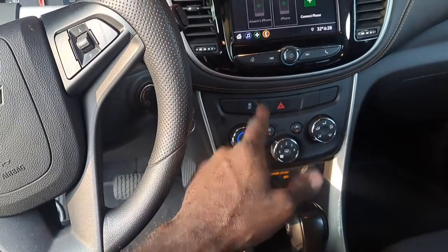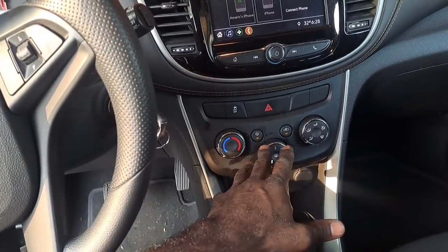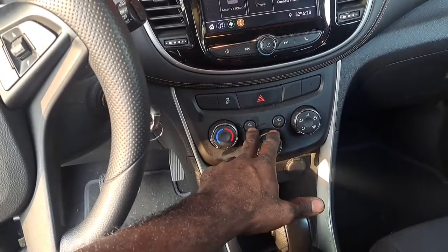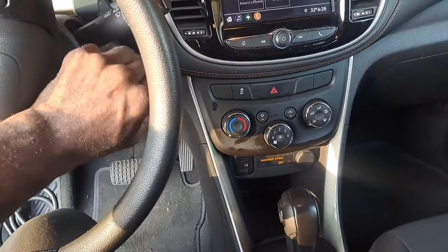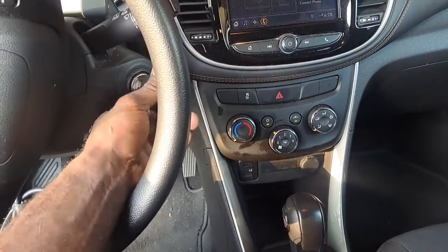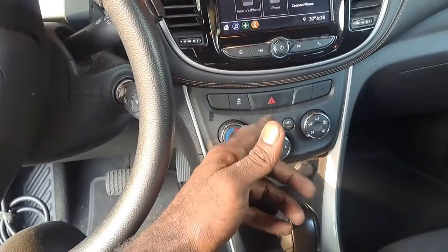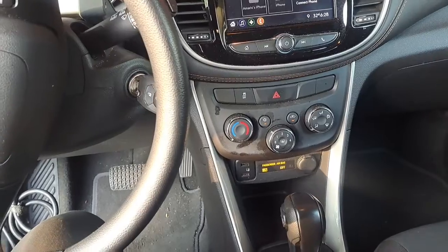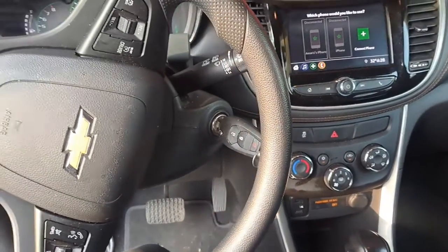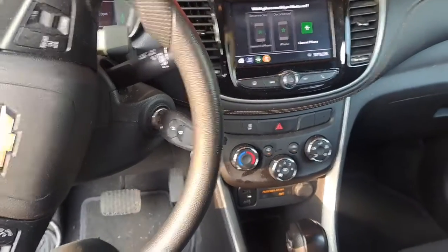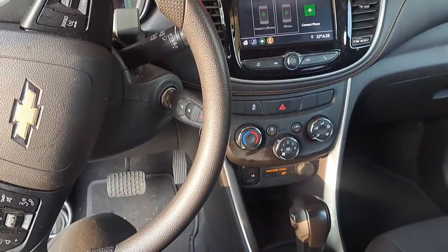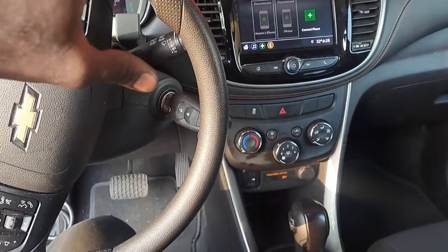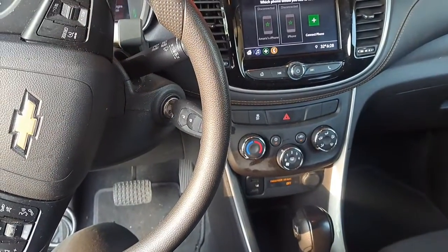And even if I go into the HVAC unit, I can hit the AC button, submit a request, and it recognizes that the buttons are being depressed. It's just not following through with activating the AC, simply because the ambient air temperature sensor is at -40. Let me show you what it looked like, and what I found out, and then we'll go on with discovering the problem, because I'm midway through it and I think I'm getting really close.